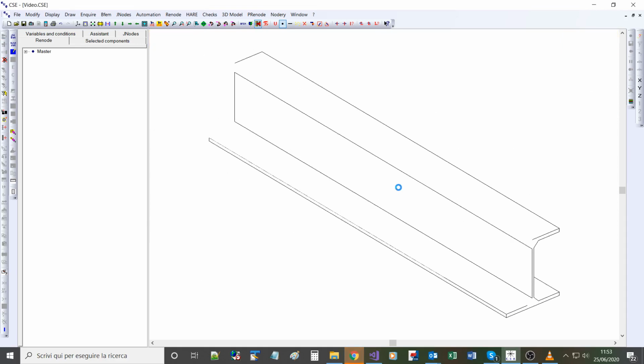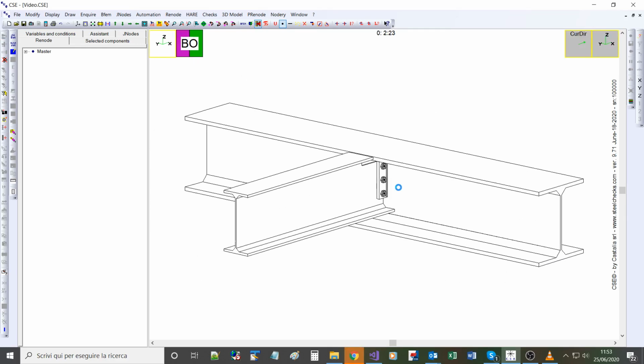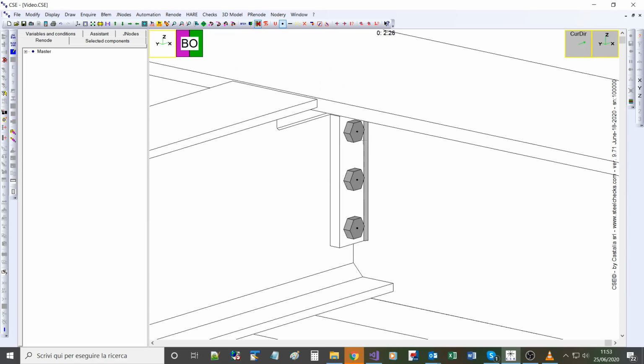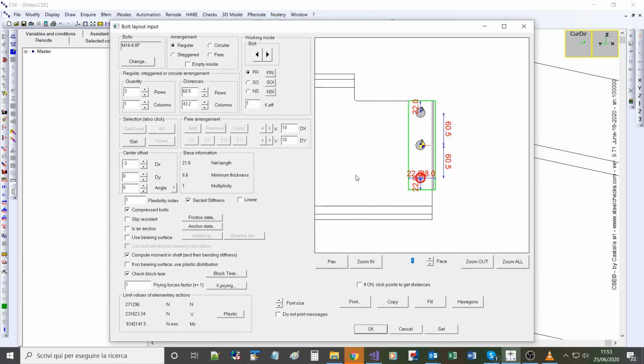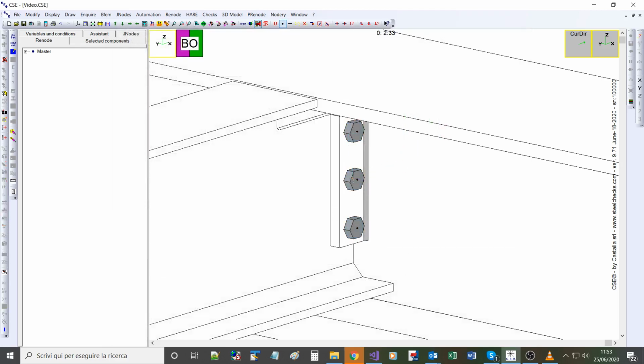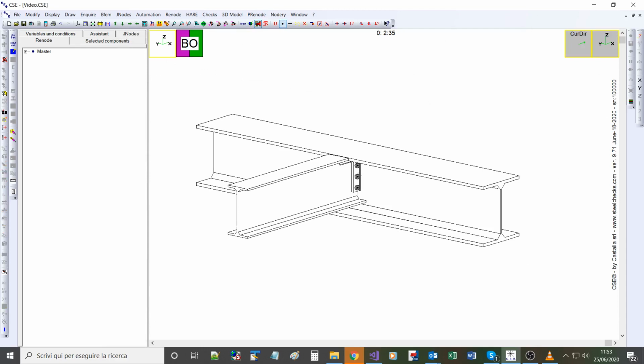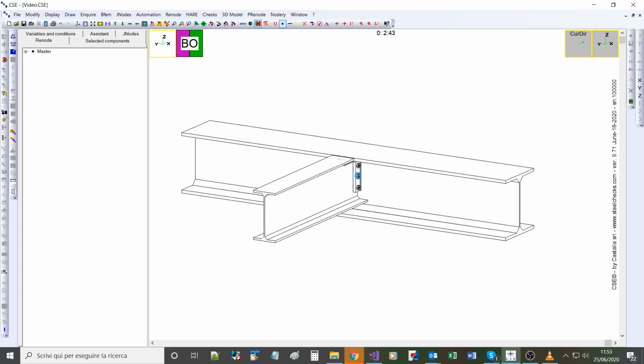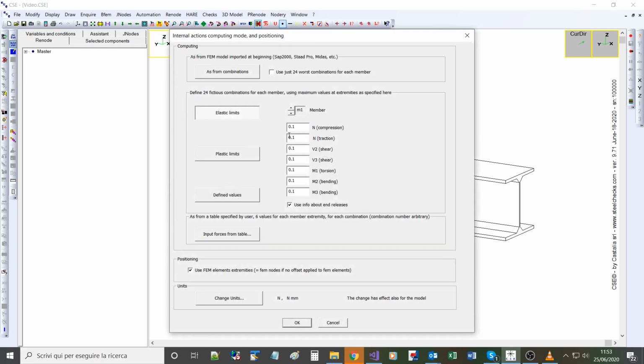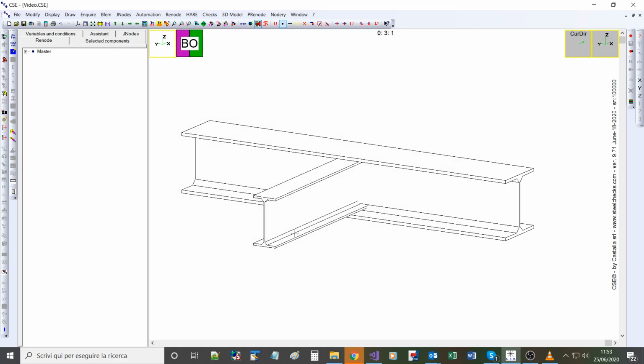And as you see, there is a single fin plate with a column of 3 bolts, which are M16 bolts. This is the result of the automatic design when 0.15 shear limit is applied to the secondary member. Now we just reset everything to blank and set another level for the member forces. Instead of 0.15 we set 0.30, which is twice as much the force.